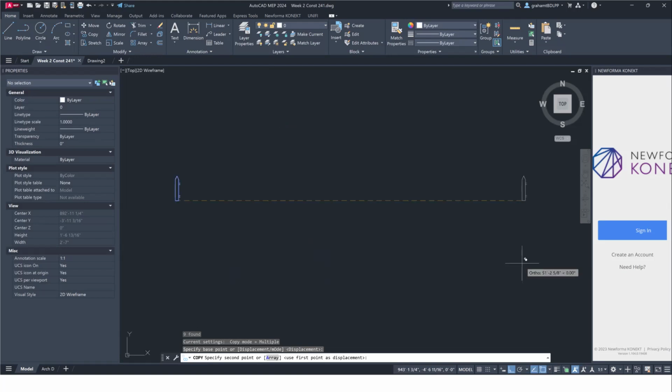What this does, and you'll see this in a second, is when I paste this, the next item should automatically be copied, right? I can keep copying this down and down and down. If I copied it right here, 8.5 inches over, the next one is going to try to place it right on top of each other, or somewhere up or down. But by bringing this ortho line way out there, I could type in 8.5 inches.